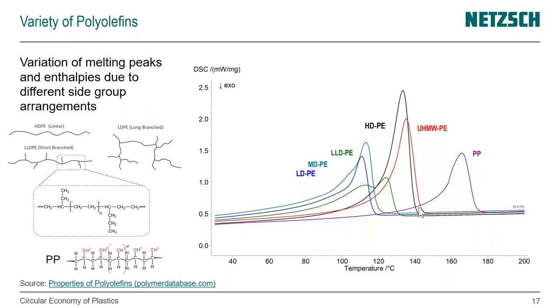I'm just taking the PP peak here, try to disregard the other curves. So this here is the melting of very small crystallites. This is the melting of crystallites that are a little bit bigger. So this is really what's happening as the material is melting. We have larger and larger crystalline structures that are melting.